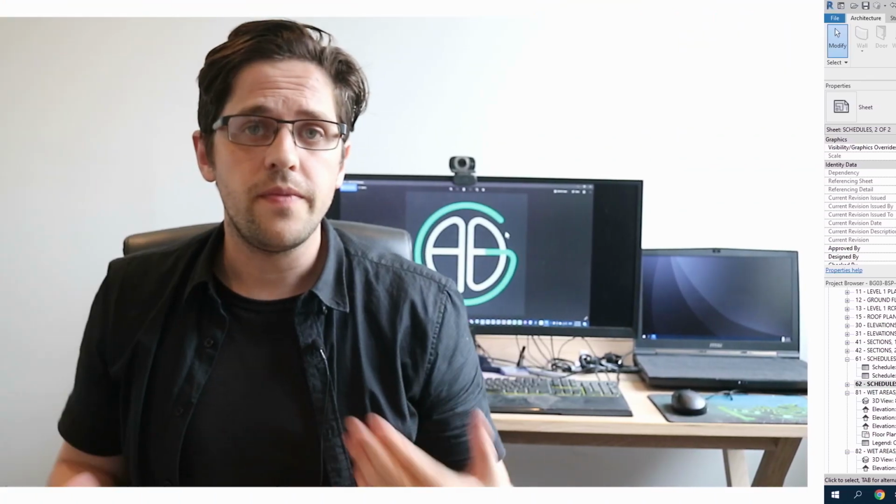In the next video, we'll have a look at actually using this data in a more interesting workflow. So hopefully that was a useful video. Obviously what I'm showing you here is just one way to go about it. Now there are things like classification schemes you can use to apply to objects to better classify them in a larger scale project. So really I'm just doing a very informal classification here. However, I guess these are the steps you could use in order to set up an effective cost takeoff workflow. In the next video, I'm going to be looking at how you can use Dynamo to extract this data to an external format, but using these parameters we've set up as a guide for how Dynamo knows which parameters are relevant per the quantity that we want to obtain.